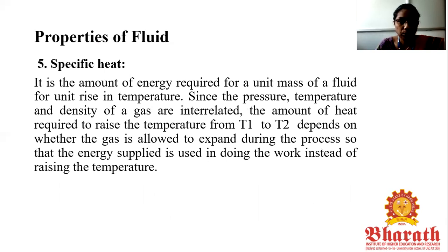The next property of fluid is specific heat. It is the amount of energy required for unit mass of a fluid for unit rise in temperature. Since the pressure, temperature and density of a gas are interrelated, the amount of heat required to raise the temperature from T1 to T2 depends on whether the gas is allowed to expand during the process, so that the energy supplied is used in doing work instead of raising the temperature. So this is about specific heat.